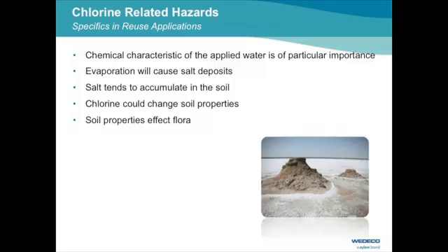And if we look at water reuse, which, as far as I heard over the last days, is a more and more important topic in this area, it's also probably not the best choice to add chlorine for disinfection. If it's used for irrigation, you may have salts generated on the soil. There will be an increase of salt level over time if you continue to use chlorinated water reuse for that purpose.